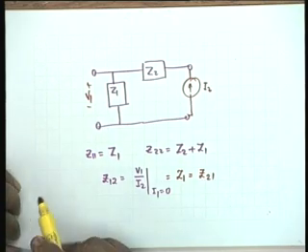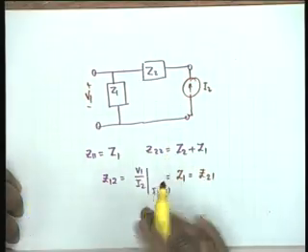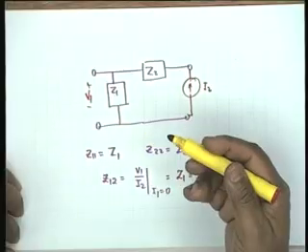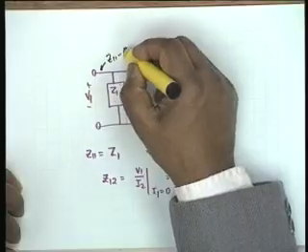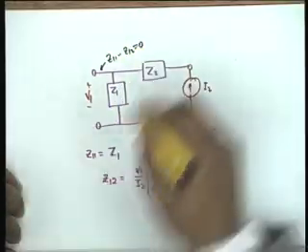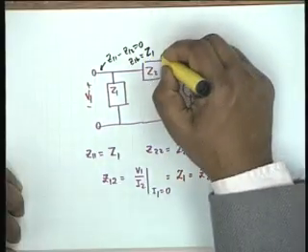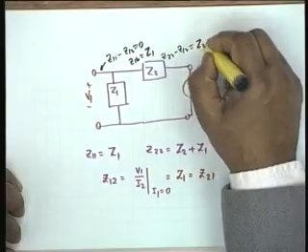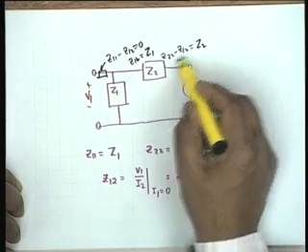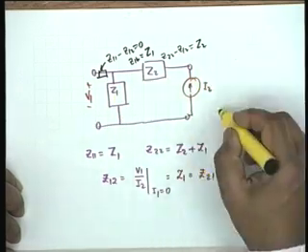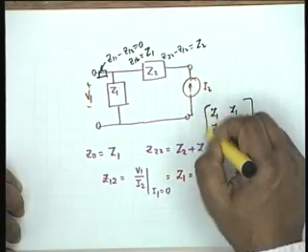Now there are many ways of looking at it, okay. This is one way. The other way is you compare this with the T equivalent circuit. Alright. In other words, you write Z11 minus Z12 equal to 0, short circuit. Z12, the shunt element, is obviously Z1 and Z22 minus Z12 equal to Z2. Alright. This element is 0, this is Z1 and this is Z22 minus Z12, and therefore it gives the same results, that is Z1, Z1, Z1, Z1 plus Z2. This is the Z matrix.